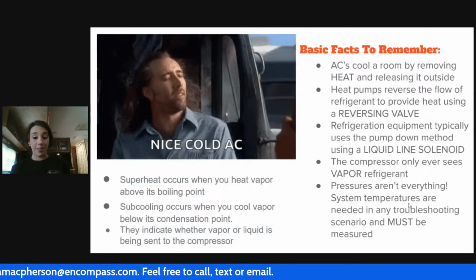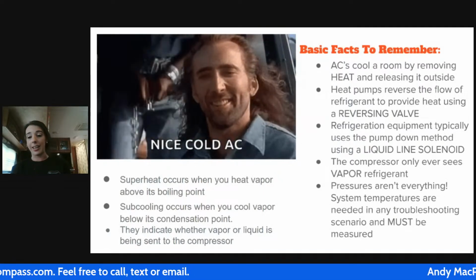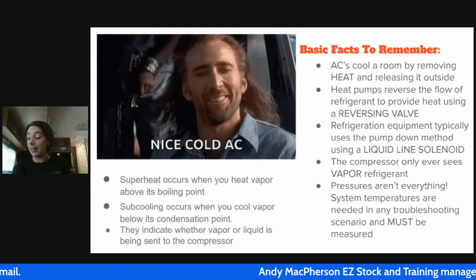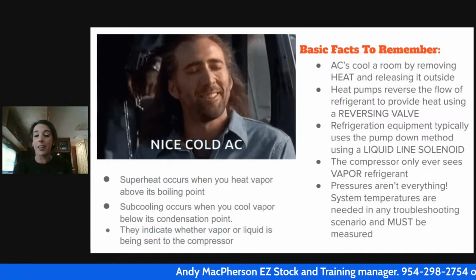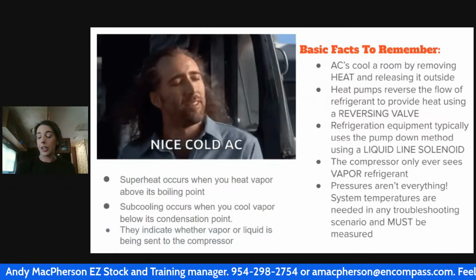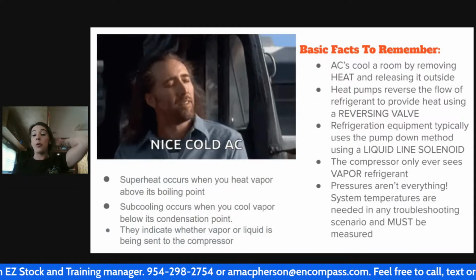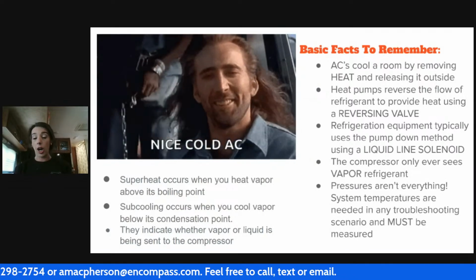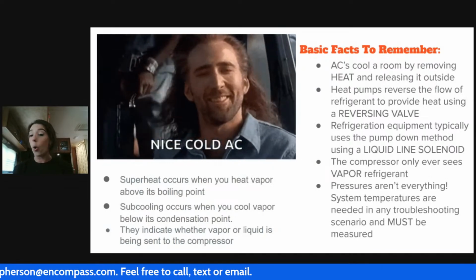Pressures aren't everything. For decades and decades, we only had pressures to go by. And then if we happened to have someone kind enough and smart enough to teach us the calculations, yeah, we could get our superheat and our subcool and our saturation temperatures. But that was very few and far between. And most of the time what ended up happening is our lead taught us to feel the suction line. And if it's cold, we're ready to roll.